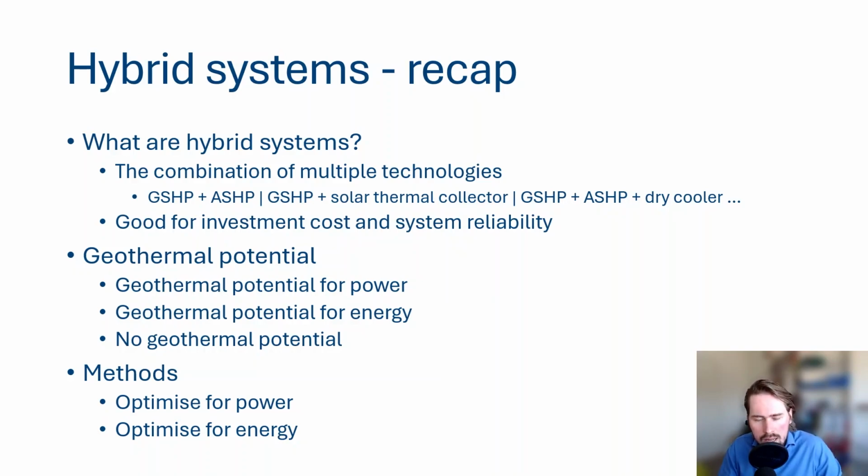So, hybrid systems are a general term for every HVAC system which has a combination of multiple technologies. For our geothermal hybrid system, it's a ground source heat pump in combination with, for example, an air source heat pump, solar thermal collectors, dry coolers, waste heat, etc. And the main advantage, we said earlier, of hybrid systems was that it's good for investment cost and system reliability.